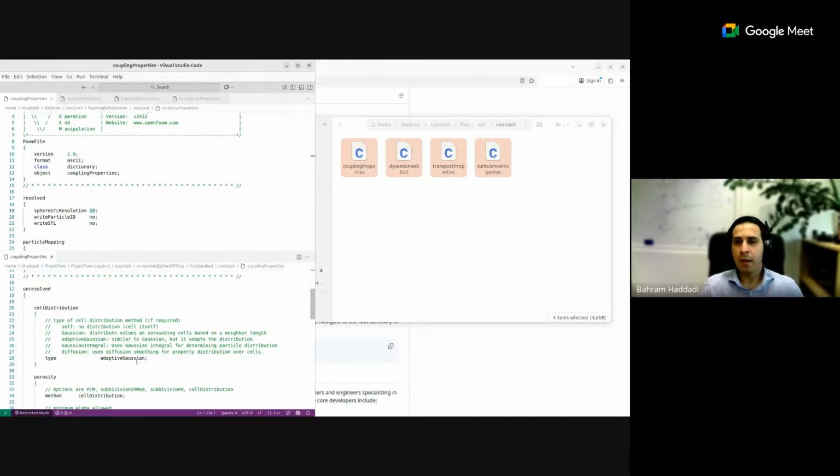If you're selecting the wrong model or the wrong settings for models, then it will end up in a wrong simulation. For those of you who are familiar with approaches like RANS in turbulence modeling and DNS: in DNS, we don't use any model. Its computation is super expensive, but whatever comes out is correct and accurate. In RANS, on the other hand, it's very cheap in computation, but if you make a slight mistake in the setup, then the results are not reliable anymore. So this is not a perfect one-to-one comparison, but I think they're quite close, also in this sense.